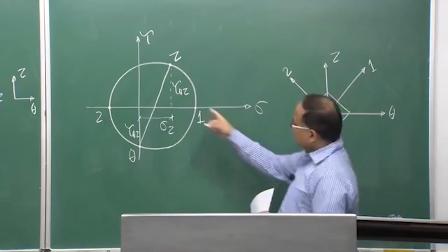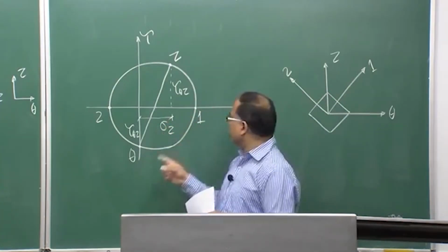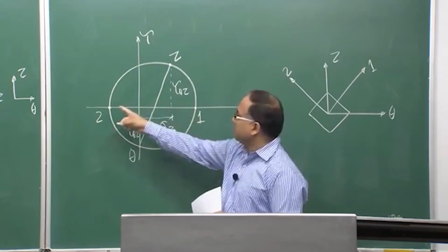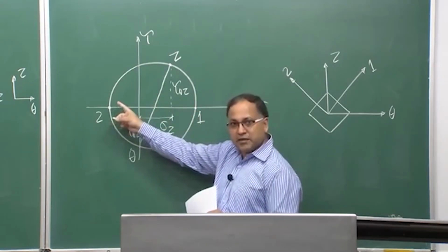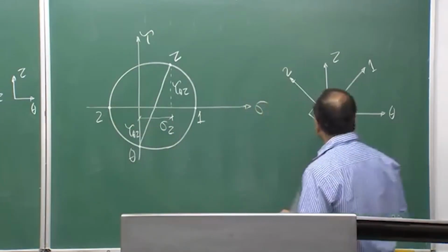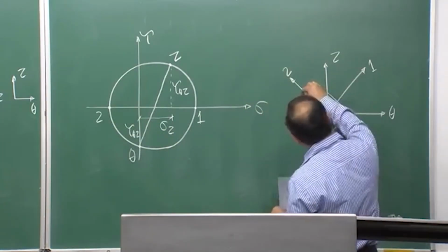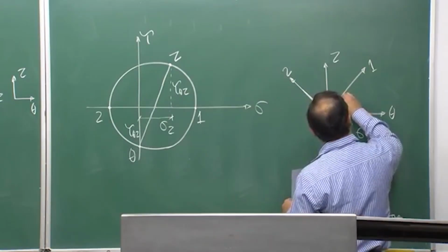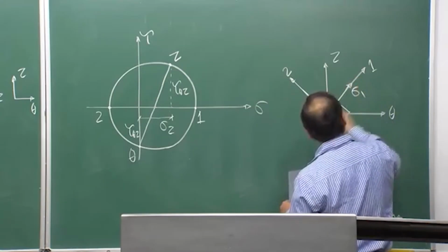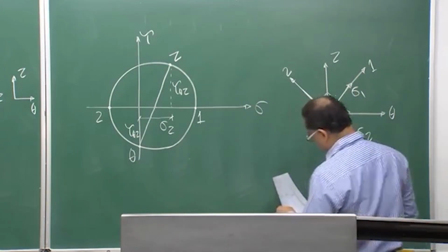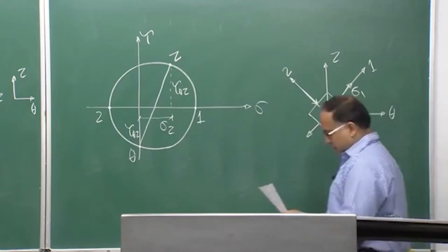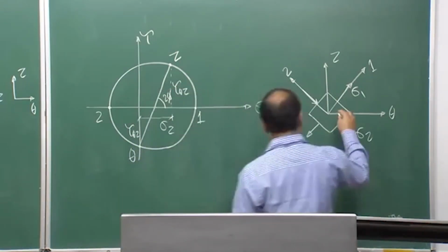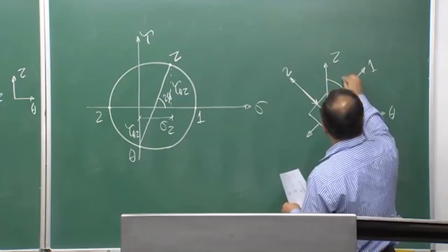And if you look at this figure, this Mohr circle, major principal stress is positive, okay, that is tensile in nature, and minor principal stress is negative, that is compressive in nature. So, therefore, I can show this is my sigma 2 and this is my sigma 1. Okay. And if this angle is twice phi, then this angle is also phi.